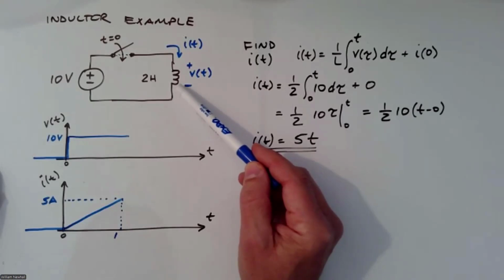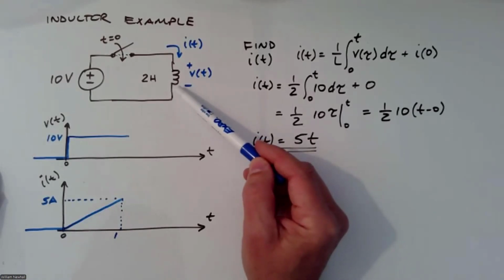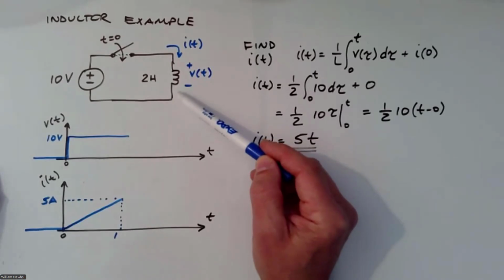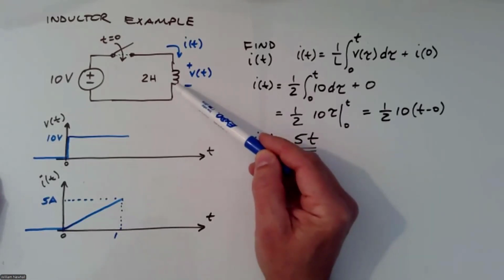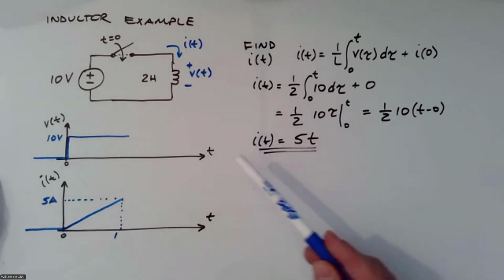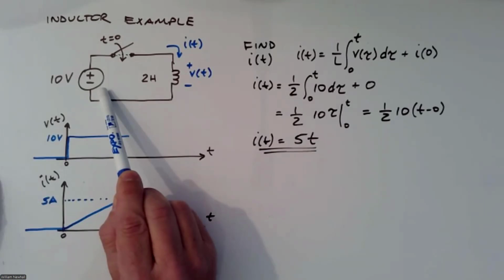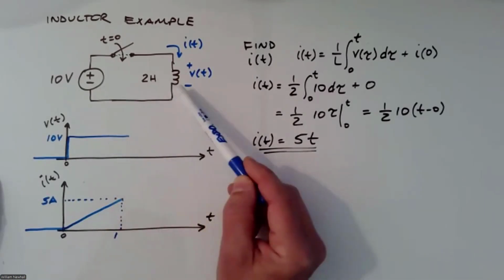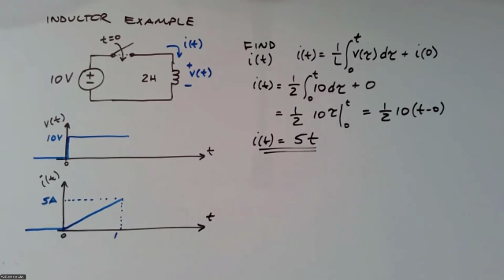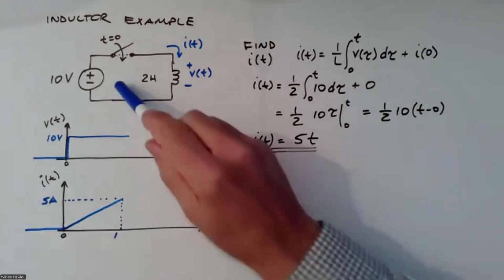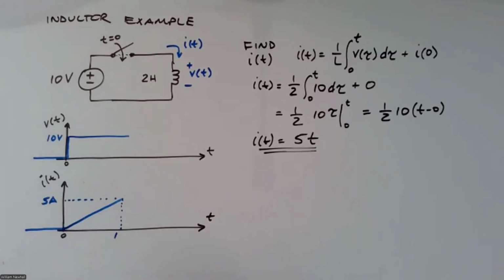The wire does have resistance. If it's made of very thin wire, that wire is going to get hot when you put too much current through it. It's basically going to look like a small valued resistor. Eventually, the power gets to the point where you burn out the coils of wire. So if this is a kind of hefty gauge wire inductor, then you probably hit the current limit of the power supply, or you burn out this wire. So something probably unintended is going to happen if you do this in lab. Okay.